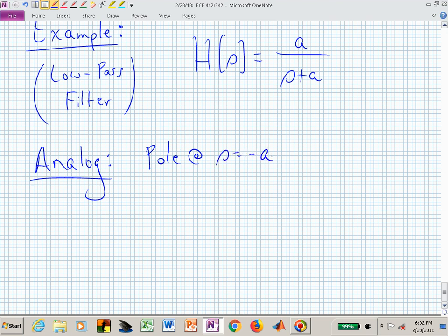Do you see the Bode plot for this? It would be, well, I'm giving out the answer. Do we have any finite zeros? No, there's no finite value of s that causes that H of s to vanish or to become 0. So we have no finite zero.